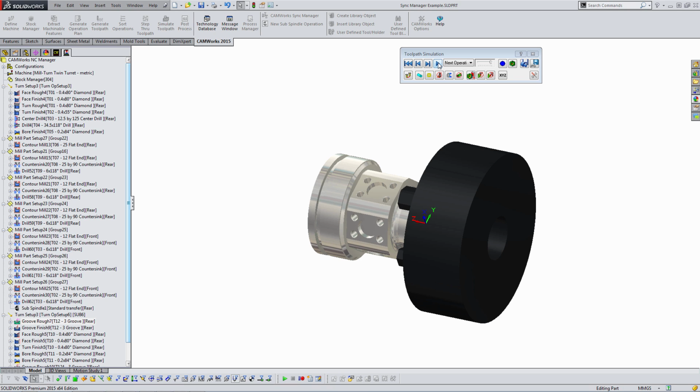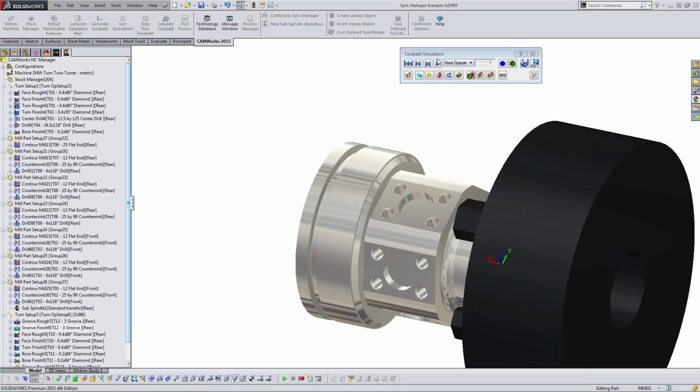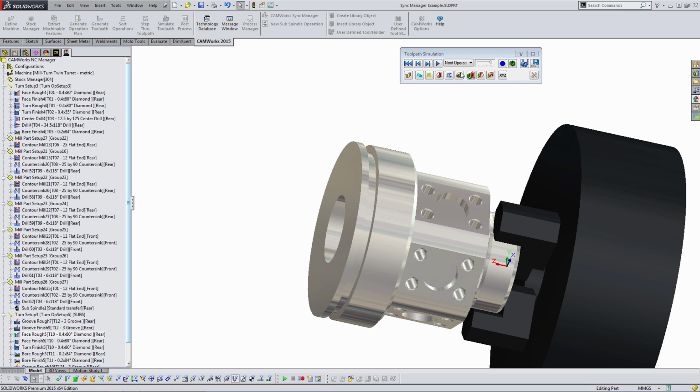So just continuing on with this simulation, there was a transfer from the main spindle to the subspindle. That's programmed directly into the software. We have templates set up in our post processors to allow you to say, at this point, we want to do a transfer, or we want to come in with the subspindle and just grab onto the part and hold it with both spindles. We can do pretty much anything you need to do on the subspindle. In this case, it just transferred and pulled it back. And now there's some grooves being cut from this side and some ID boring operations as well.